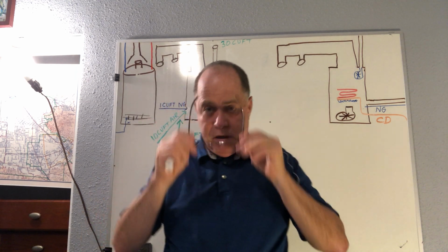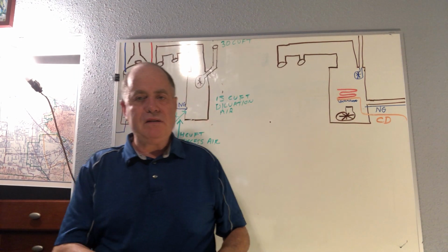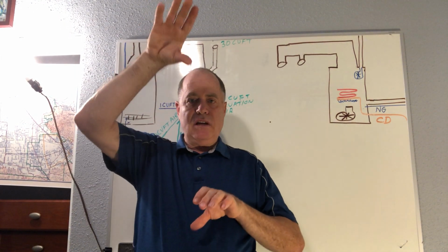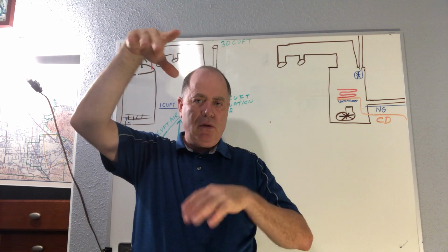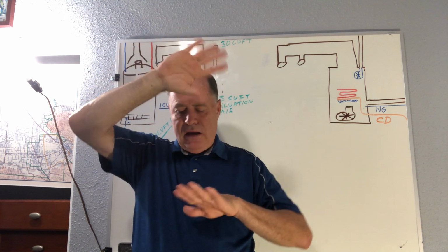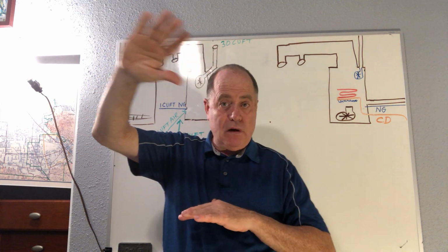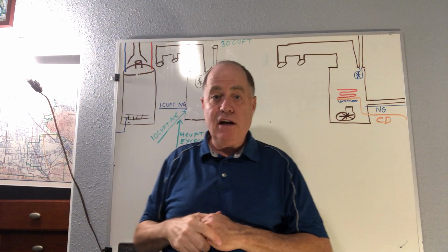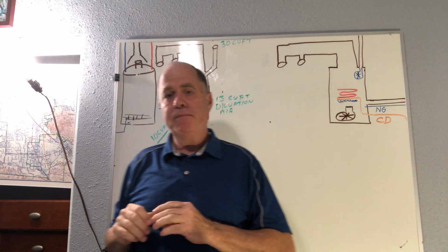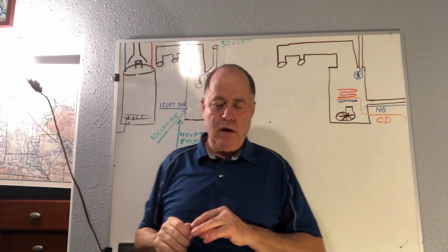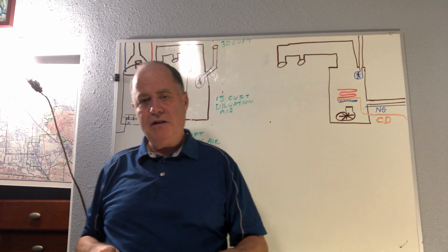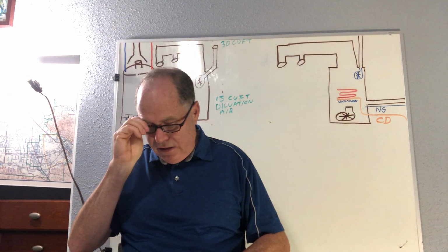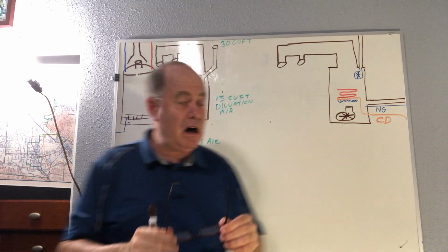And again, with the openings, the one and two openings concept, they need to be within like 12 inches of the ceiling and 12 inches of the floor, not directly, and up off the ground so things can't build up and block that. And that's what you see in a garage, right? When you have these air vents, one's near the floor within 12 inches, the other one's near the top of the garage. Let's talk now about these more modern furnaces.